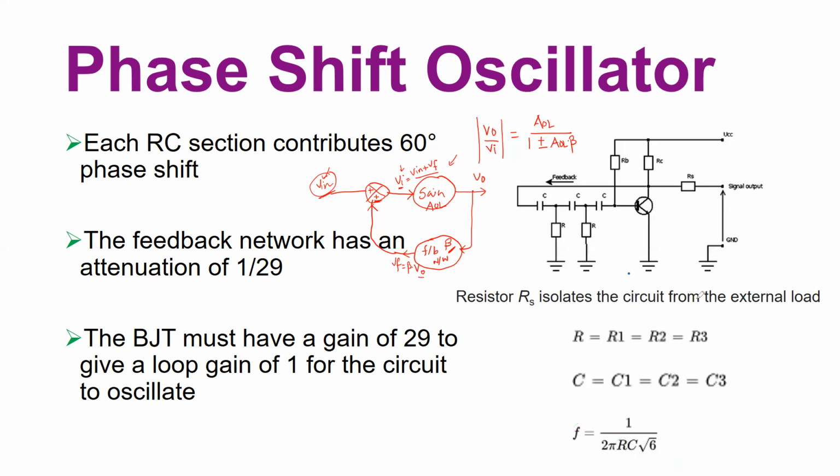Okay, so just put that value and make sure that your circuit will then oscillate. It will reach the steady state. As soon as you switch on this DC voltage source, your circuit should start and then sustain an oscillation. If the initial gain is greater than 1, the oscillation will start and grow, and then it will sustain and saturate to a constant level. That's because the circuit's gain will saturate, so that A times beta is exactly equal to 1.